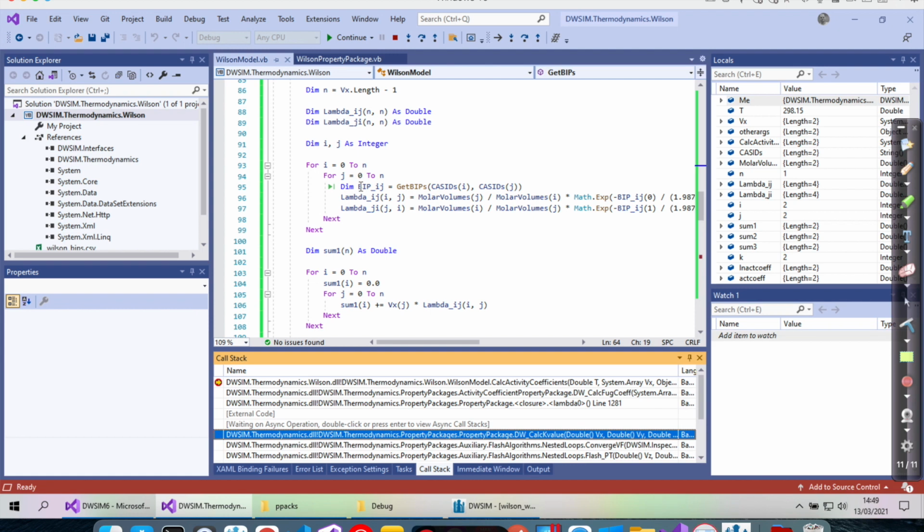I know. I got it. So when you have a separator, you're not at equilibrium. By the way, you have some mixing volume. That is what it is, and then you start splitting, and you have some unit operations that have deviation from the equilibrium. This means you can call it efficiency, and there are many ways of modeling something that is not exactly the equilibrium. If you work in oil and gas, you know that the equilibrium for a vessel is almost never reached. You have 1% of the equilibrium, so your software is doing too well for representing the actual plant.